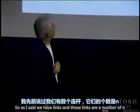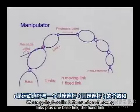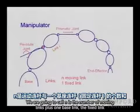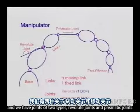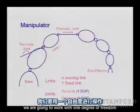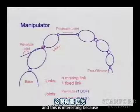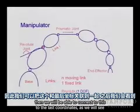So, as I said, we have links, and those links are in number of n. We're going to call n the number of moving links plus one base link, the fixed link, and we have joints of two types, revolute joints and prismatic joints. So the idea is we are going to work with 1 degree of freedom joints, and this is interesting because knowing that we have only 1 degree of freedom joints, then we will be able to connect these to the generalized coordinates, as we will see.